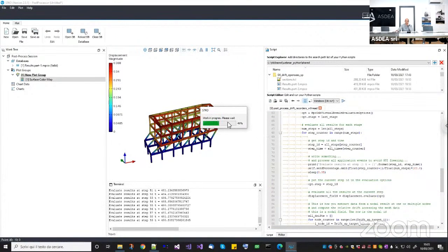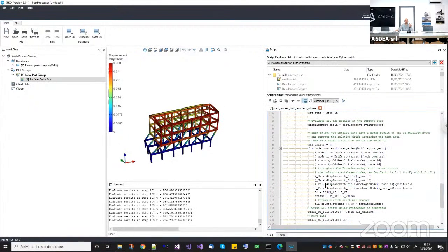I think we have a question. In the displacement object, will the length of the element change? No. The length is the length of the mesh in the undeformed configuration, okay? So if you want to know what is the deformed configuration, you can just add the total displacement, okay? So this one mesh is the initial mesh, okay? So it will not change.